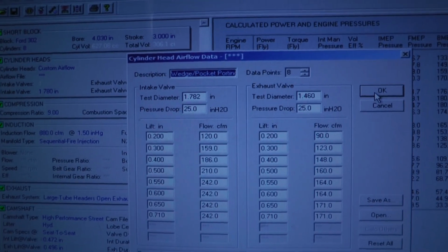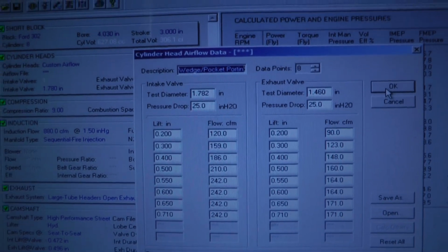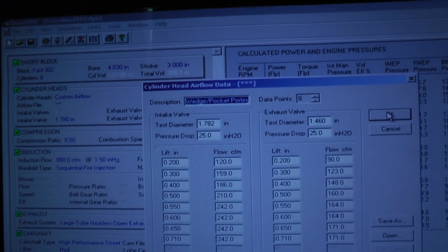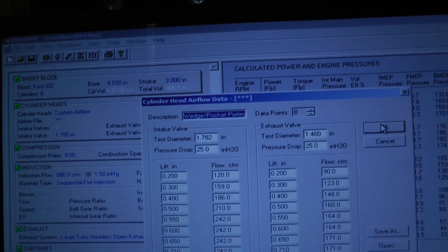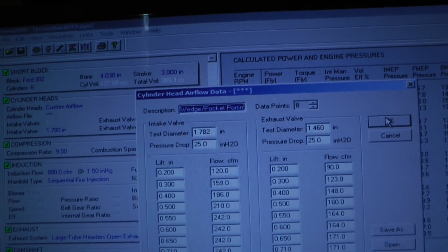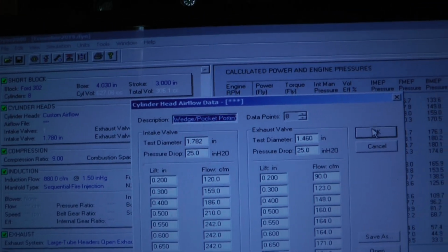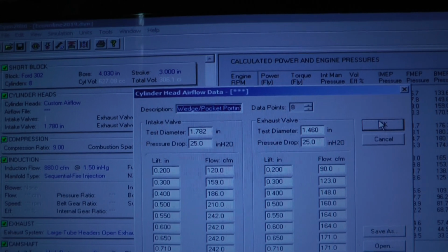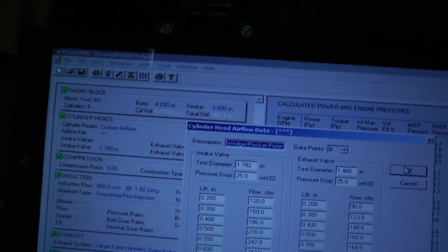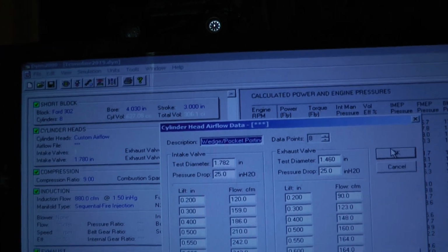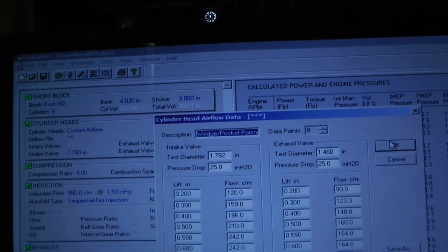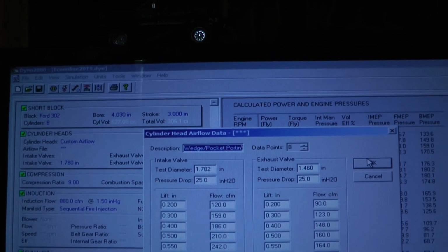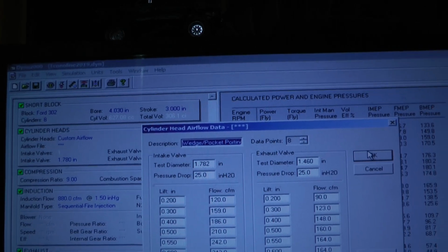they really don't gain anything from lifting more than 500 thousandths, and that was part of the reason why I did the cam selection that I did, and kind of built all the ideas around that one thing, being the limiting factor, the ceiling of the stock iron heads. Because a lot of people will choose a camshaft based on sound. They go by lift numbers, basically kind of thinking that they're maximizing when they're kind of wasting valve events.